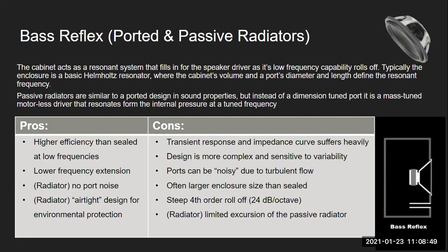The reason why this has become very common in the past 10 years, I'd say, is that think about a lot of those Bluetooth speakers. They want to have somewhat efficient low frequency output, but they also don't want water to be able to get into the thing because they don't want to put a hole in the box like a port, right? So for a lot of those little Ultimate Ears Bluetooth speakers, they'll use passive radiators that create a bass reflex design, but allow them to be thrown into water or something like that, right? So that's a very good benefit of the radiator design.